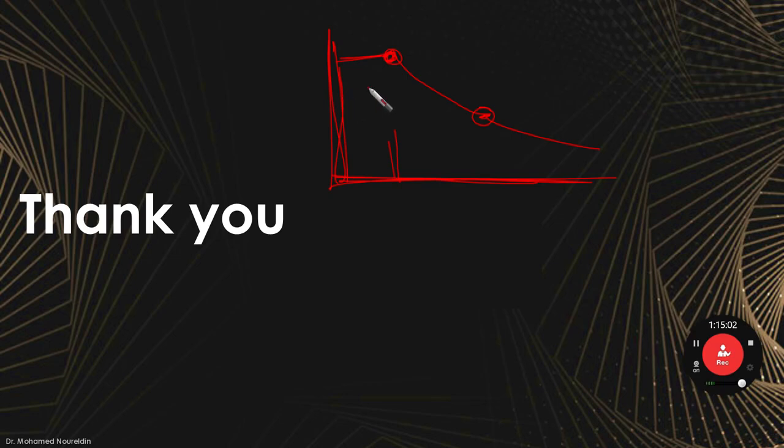And remember that we are talking about compact sections, and if we are dealing with a non-compact section, this means that the horizontal line on the curves or on the charts is going to give us flange local buckling. And if we are designing and we find some dashed line, we can always go up or to the right in order to get the lightest shape.